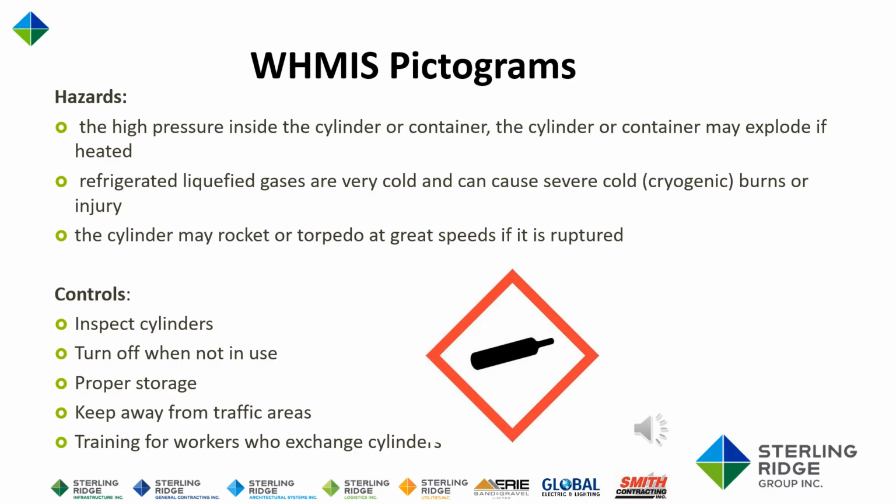Controls: inspect cylinders. Turn off when not in use. Proper storage. Keep away from traffic areas. Training for workers who exchange cylinders.